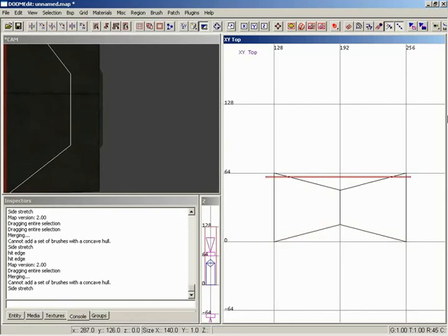So basically, what do we have? This line passed through once, passed through twice, and if that's all it could pass through, then it would indeed be convex. Pass through again, which meant that these 2 points somewhere in here had to be denting in, and then pass through yet again, so we've got 4. So yes, this would make up a concave brush if we were allowed to merge these two together.